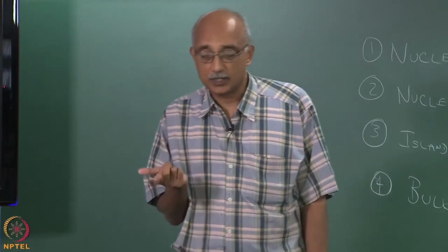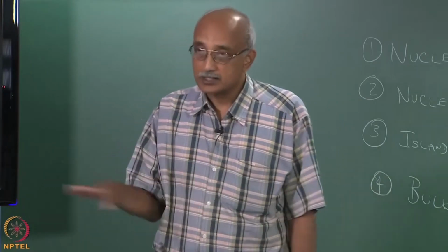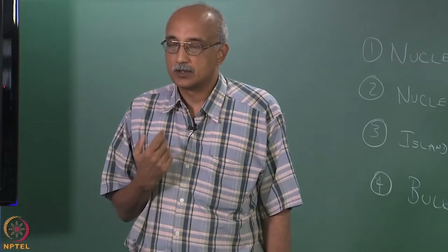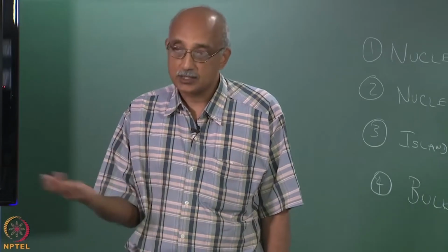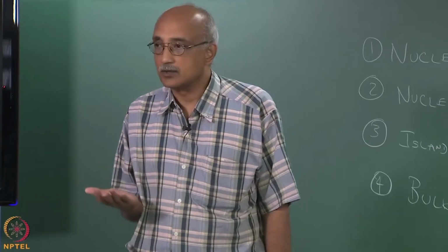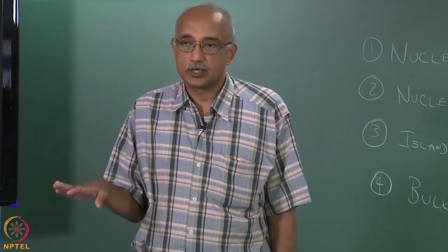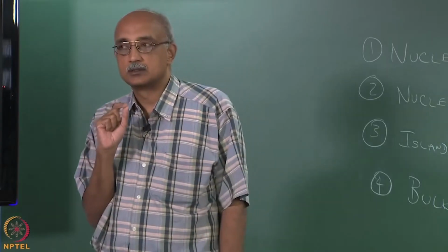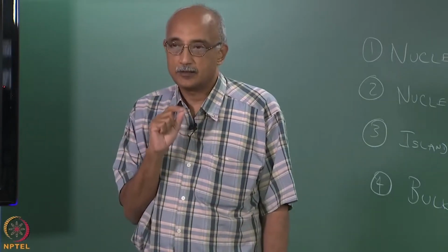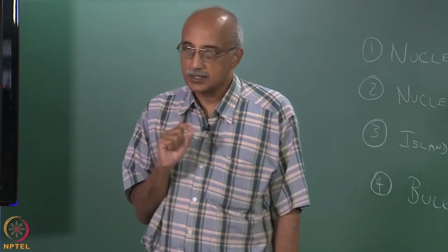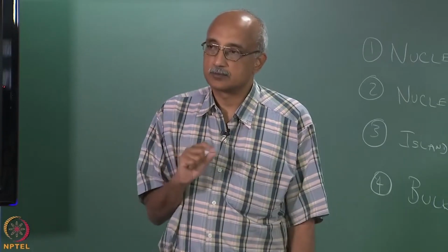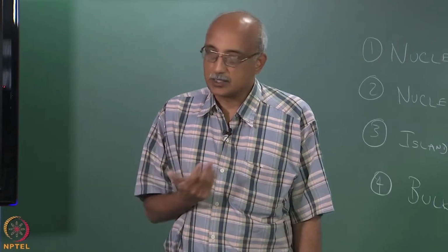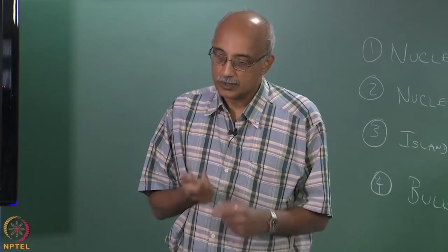Now, what can happen in that case is, instead of forming silicon semiconductor films, you might start forming silicon oxide, right, or in case where the nitrogen gets absorbed, you can even form silicon nitride type of films, which are clearly what you do not want. So, the composition is a very important parameter to monitor and maintain records of, because it is an indicator of whether your system is performing as it is designed, or you are having impurities and contaminants enter the system.